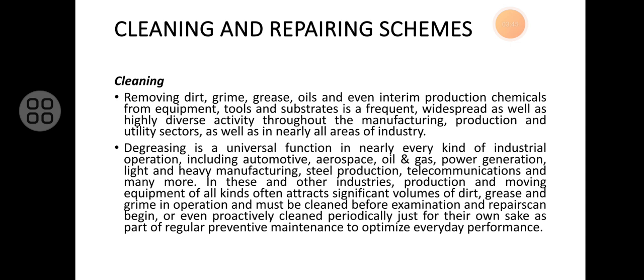The experimental results demonstrate the adhesive joint strength is significantly affected by the applied degreasing agent. Moreover, the method of application of the degreasing agent is crucial too. The result of strength testing reveals that the most effective degreasing method for hot-dip galvanized metal sheet adhesive joints is spraying using extraction naphtha.